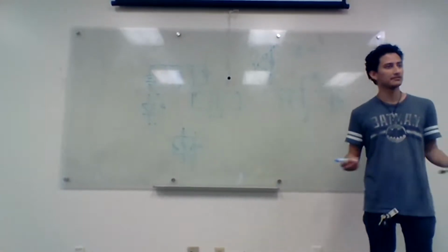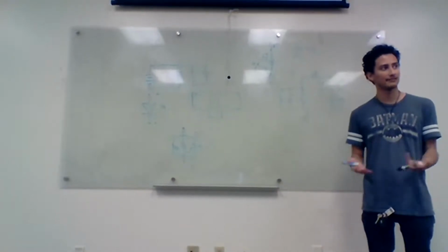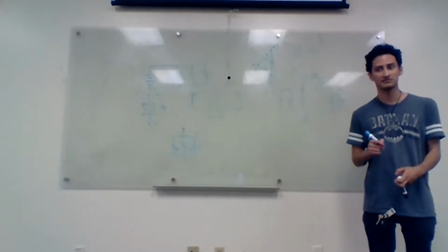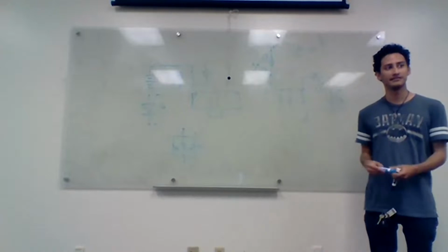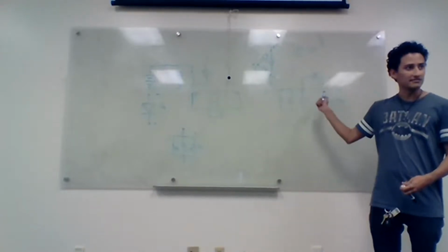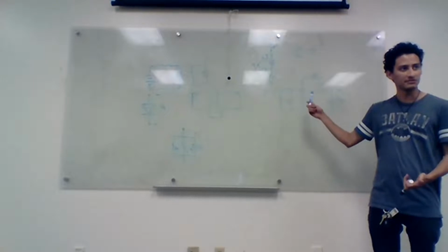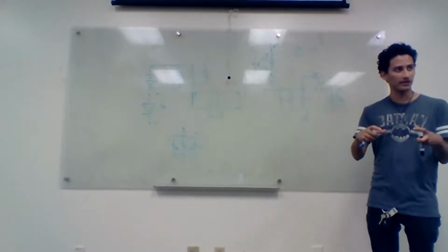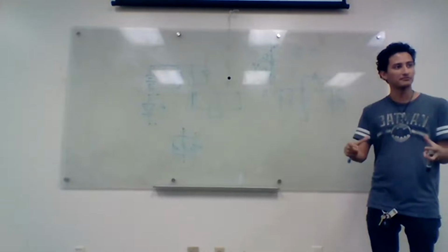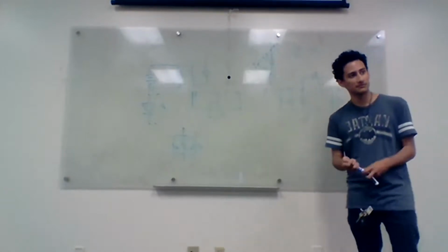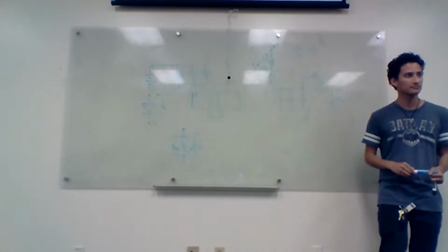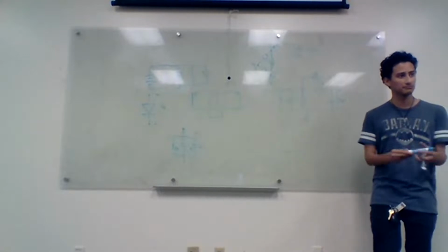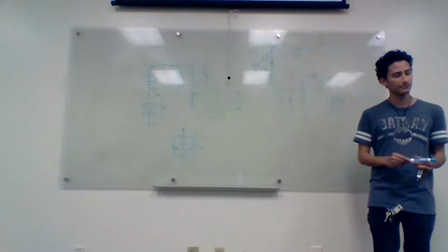So the big thing is not just copying the same shape, but understanding why that shape exists. For example, C sub D, between here, that capacitance is 0 because it's in reverse bias, and there's no movement of charges the same way as there would be in forward bias. That movement of charges is what causes C sub D to exist. So the big thing to remember is that C sub J is the only small signal value there that exists in reverse bias.